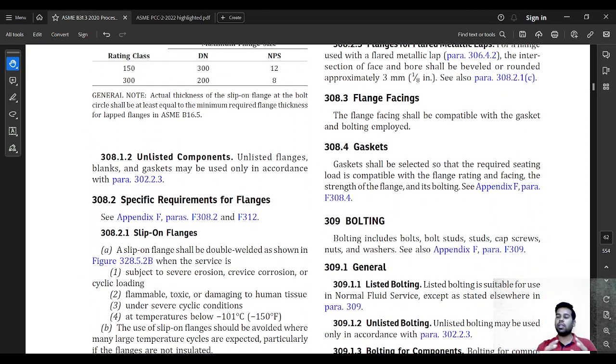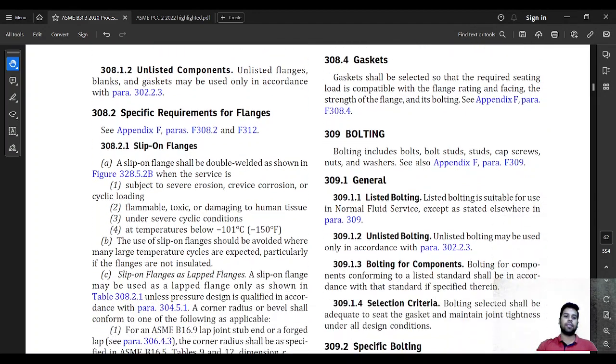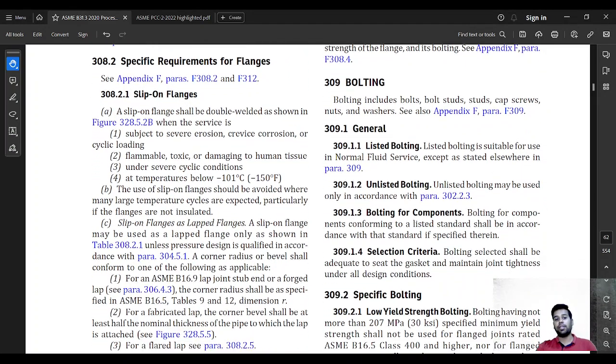Generally flanges, especially if you're talking about cast iron flanges, are not generally made, they are selected, and there is a standard for that which is known as ASME B16.5. People who are studying for the API ICP examination generally know what ASME B16.5 is. We'll talk about this when we go about solving some problems on the selection of flanges. But again, the flange should be selected based on the materials of construction and the pressure rating. Requirements for flanges: